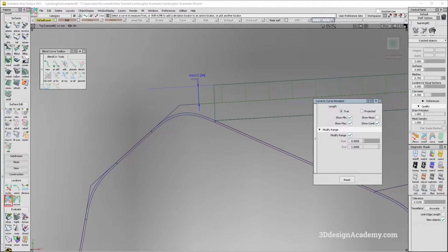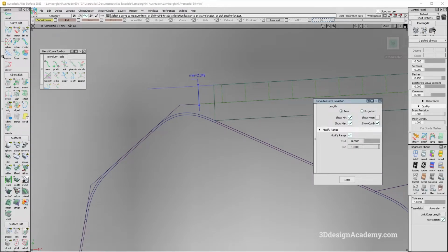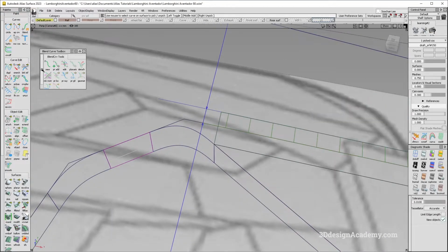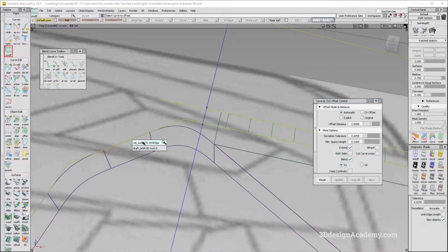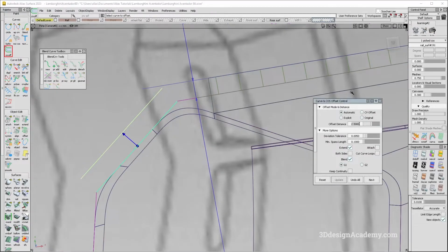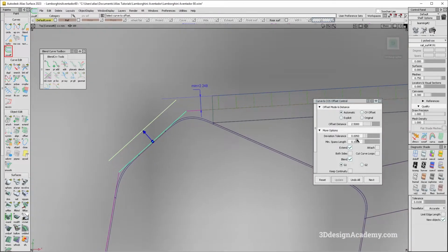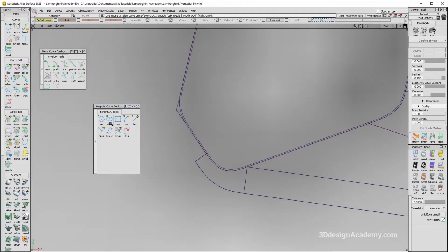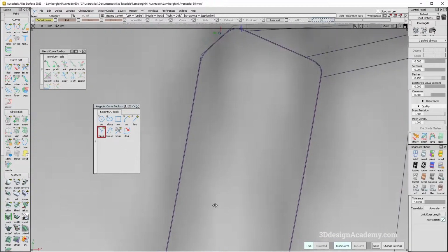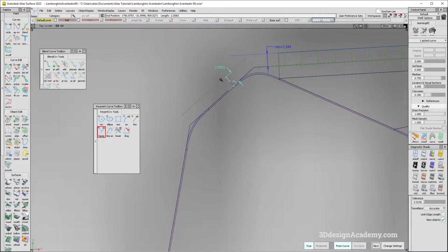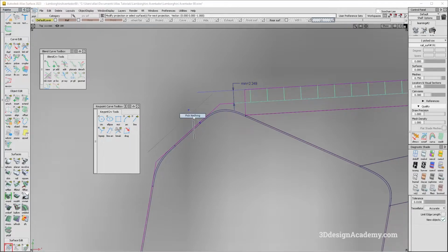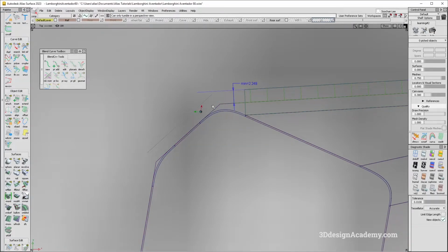And let's go ahead and I'm just going to use a curve offset to create a curve. Oh, not that one. Let's delete that. Curve offset. This, so let's make it similar. So it was 2.2, so same thing. And I'm just going to grab a key point curve toolbox, perpendicular, and I'm just going to snap it over here. And again, I'm going to project, get rid of the curve.